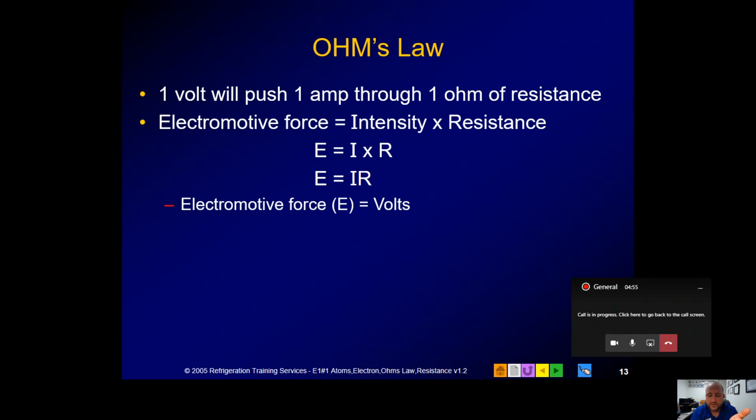So to switches, to loads. What's the difference between a switch and a load? Switches, things that pass power. Loads, things that consume power. So examples of loads would be light bulbs, motors, anything that we're trying to control to do some sort of work. And the controls themselves are switches. They're the things that's telling it when to come on and when to come off. So they're the ones that's breaking the flow of electrons.